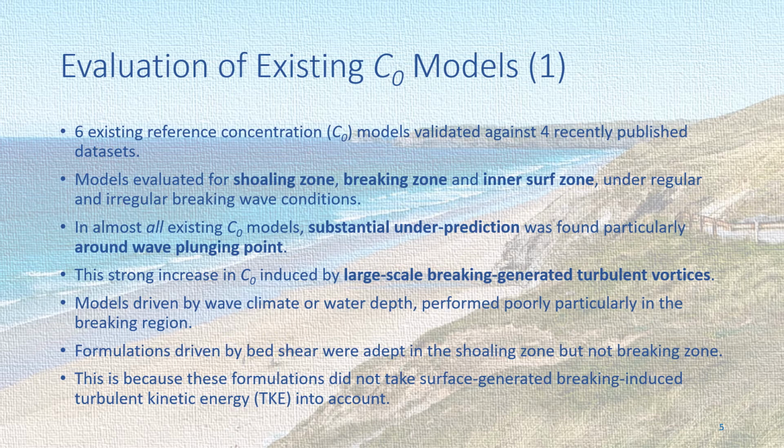In particular, models that were driven mainly by the wave climate or local water depth performed poorly, especially in the breaking region. Also, formulations driven mainly by bed shear were adept in replicating the measured concentration in the shoaling zone but not in the breaking zone. This is because these formulations did not take surface-generated breaking-induced TKE into account.